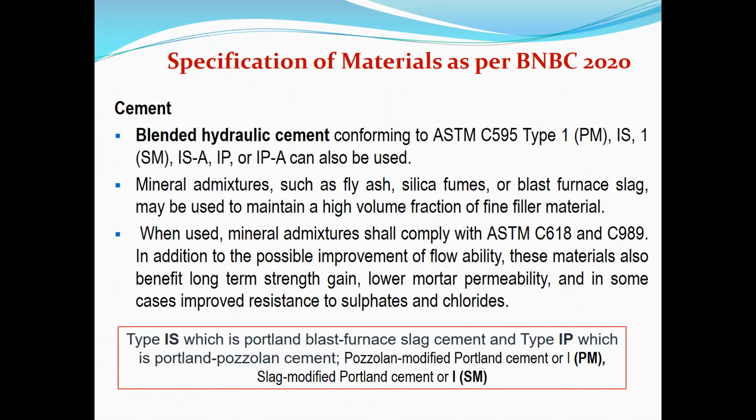These specify what the requirements of the mineral admixtures should be. Mineral admixtures also have some other roles. In addition to improving the flowability, they also contribute to gaining long-term strength and lower mortar permeability. And in some cases, they improve resistance to sulfates and chlorides. So mineral admixtures are used to gain these benefits.